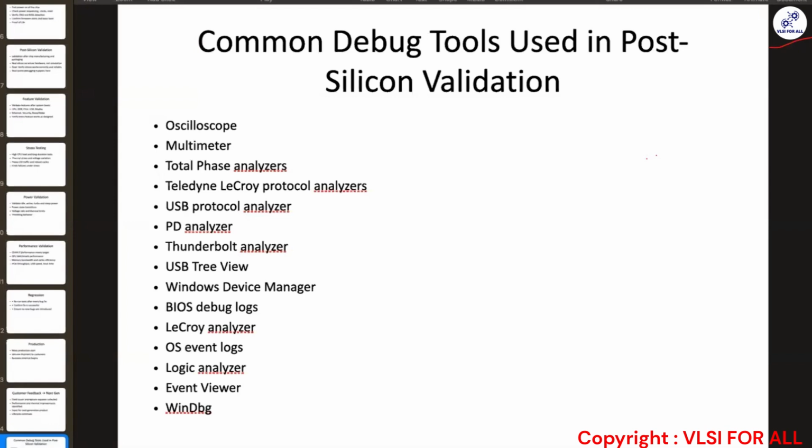Okay. So Thunderbolt analyzer, there is no specific analyzer as such for Thunderbolt. You have certain tools which are specific to Thunderbolt. This is Intel and Apple proprietary, basically. Thunderbolt is more like a protocol. So there will be internal software which will be able to understand how that particular domain is working: whether it is achieving what it is supposed to, what the speed is, whether the link is up or not, whether the link is going to low power mode when needed.